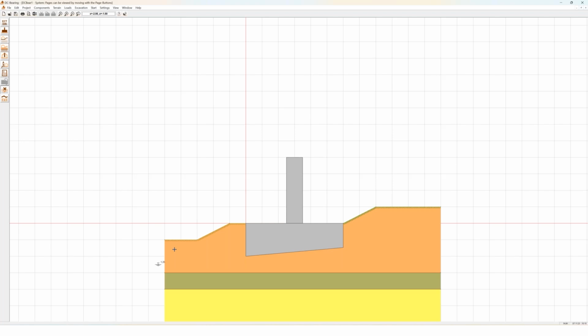So in this way, the values in a greater depth with higher soil load have a larger influence on the verification. And with this method, it's possible to weight the values of Phi, C, and gamma also when the values have a greater difference, with more than 5 degrees.